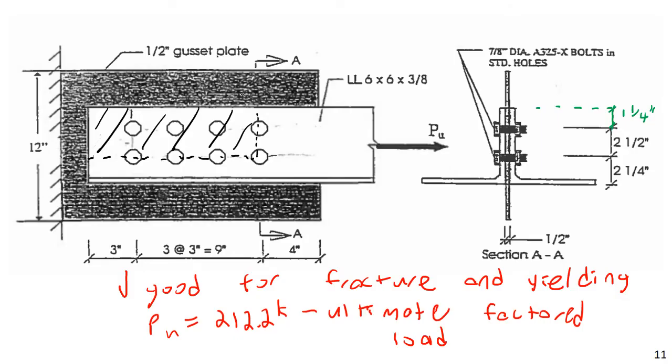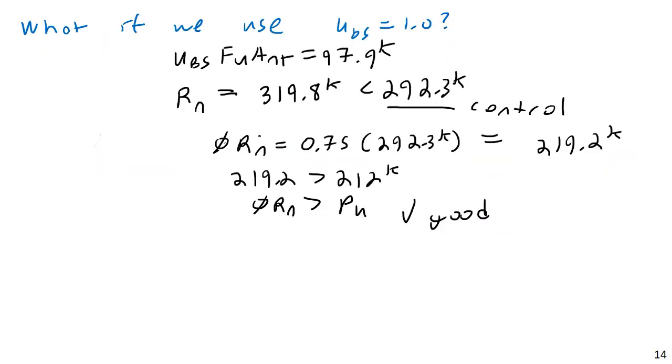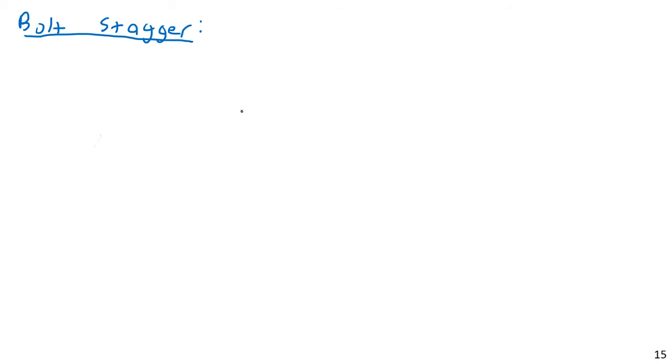If we go back here, you can see that this is a case where we have bolts that aren't staggered. Everything is perfectly lined up in nice columns, and so you know that a failure plane is pretty much guaranteed to occur along this. Failure is always going to go along the path of least resistance, and if all the holes are lined up equally, you're definitely going to get failure there. However, what if you have something more complex? Our way of dealing with this is a rough, more empirical method. It's a very simple way, but it does work.